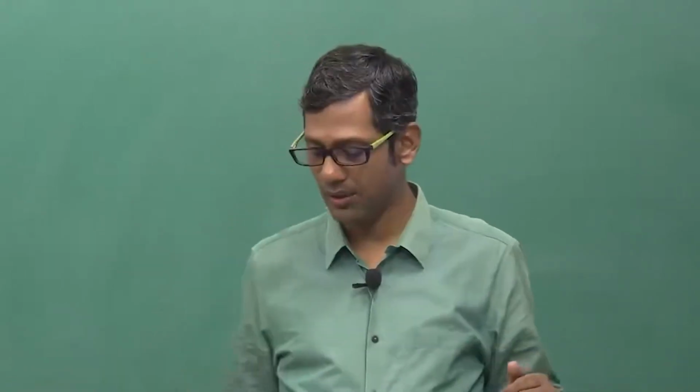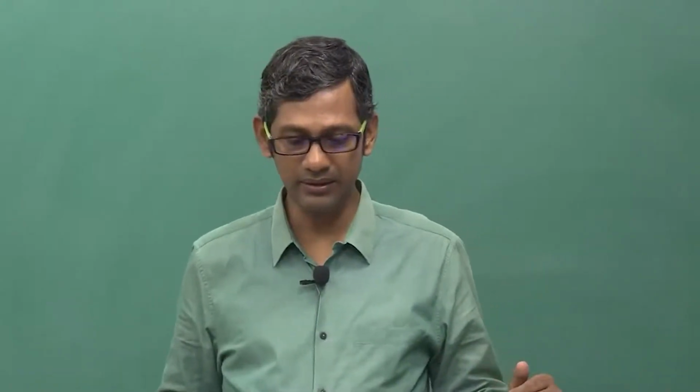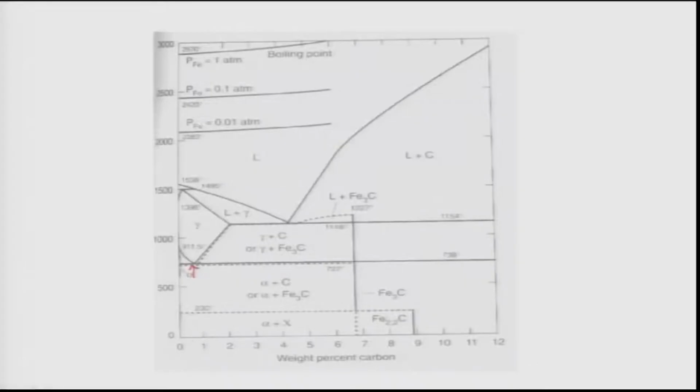Okay. Or if you want, let me go back to the phase diagram and explain again. Yeah, here it is. Suppose I take about 0.6% carbon steel and directly quench it from 950, somewhere here, to 400 degrees Celsius, here. It should transform into alpha ferrite, as proeutectoid ferrite, and pearlite, as you have seen in the microstructure. But only if we cool it slowly can it happen that way.